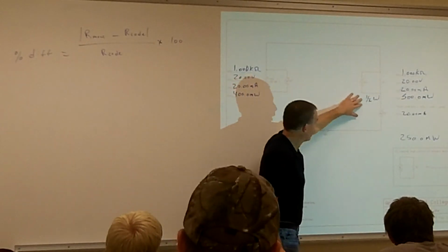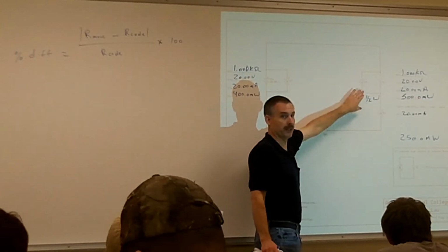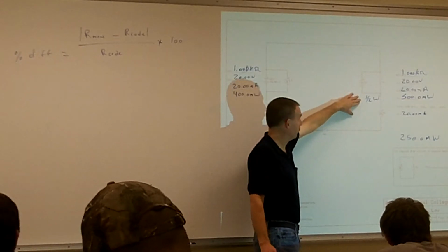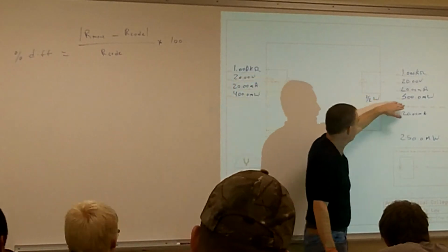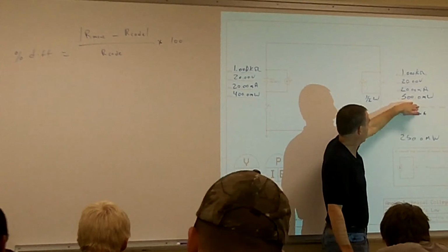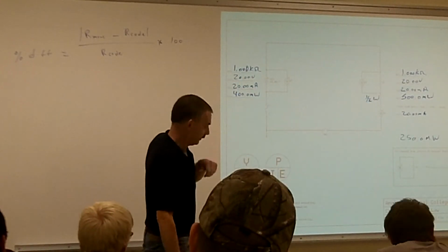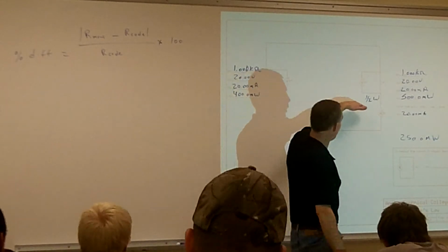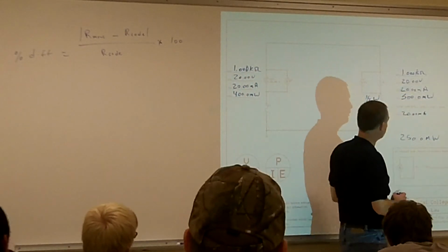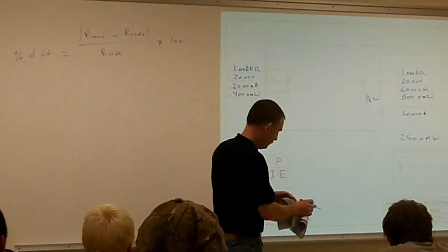This resistor would work for it, but it probably wouldn't be the best choice. You probably want at that point to be running so close to the borderline of it that if we want it for reliability, we probably want to jump that up to a 1 watt. Now, if we're selling it as a customer component, then we probably want to run it right at 500 milliwatts,